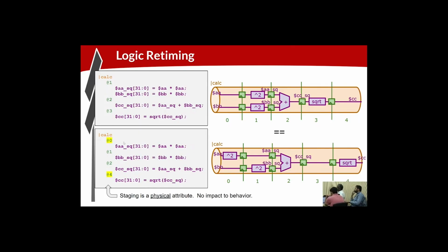Yeah, so in this example, I didn't explicitly have any logic in stage 3, so there was no reason to have a stage 3 in the code, right? Of course, that stage exists. It just has no logic in it. So in TL-Verilog, the vast majority of your code is your logic expressions. The context is fairly lightweight, and these other things, the signal declarations, the flip-flops, all this stuff comes automatically. So it's very much just, what's the logic in my model? What's the context? I give myself context, and then the bulk of what I'm doing is expressing logic.